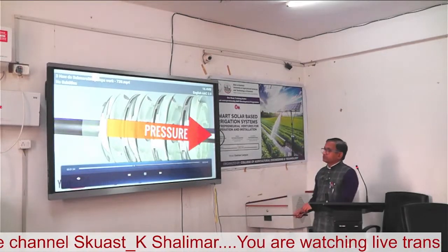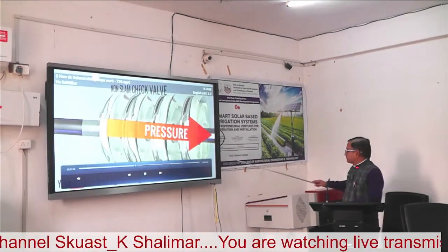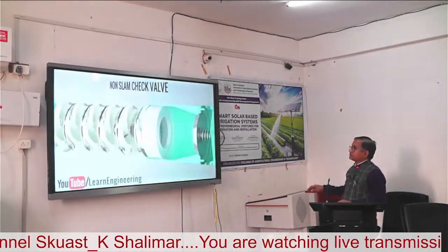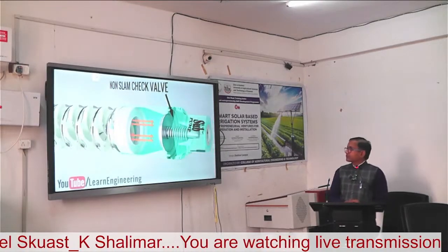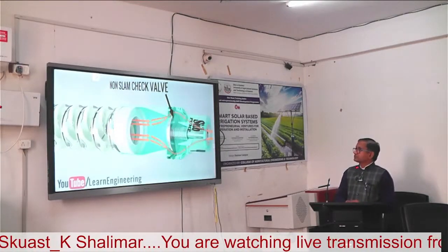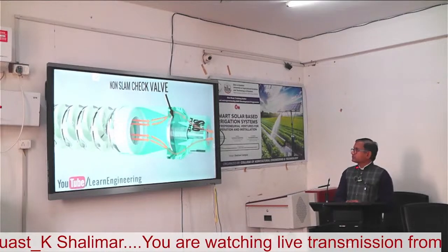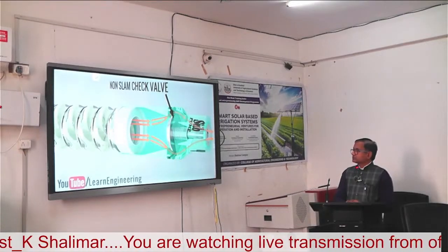So the water, so pumped, passes through an inbuilt non-slam check valve of the submersible pump. The issue of water hammer, which is a huge issue in high-altitude pumping, is effectively reduced by the non-slam check valve.